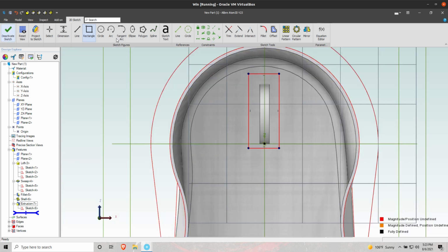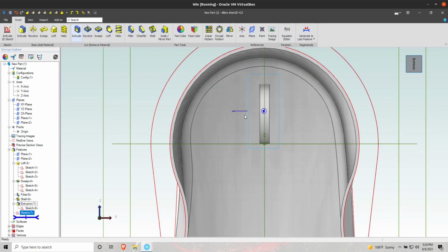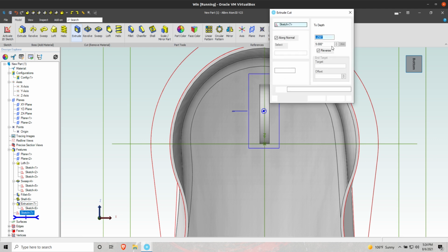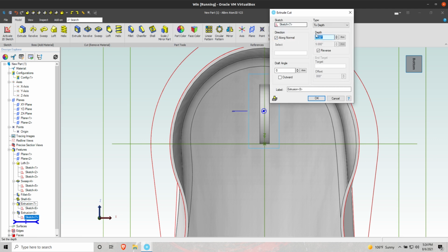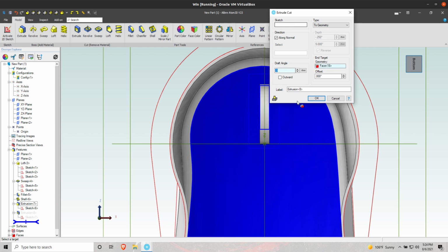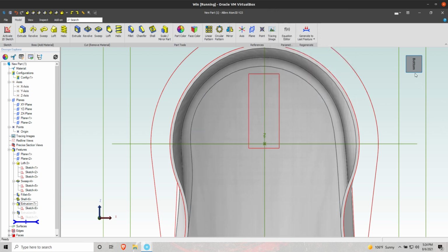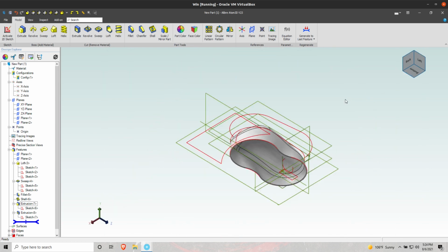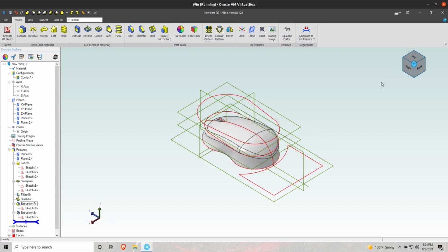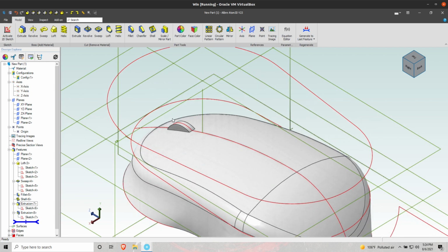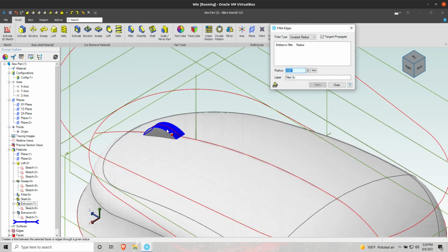We'll deactivate and we'll choose extrude. We're going to say to geometry. And I can choose this face as geometry. And it makes that wheel disappear like a magic trick. So that's a great way to get rid of a feature on a NURB surface if you ever have to do that. Okay. Maybe I'll scroll in and fill up my mouse wheel. And then I think for the purposes of what I'm hoping to accomplish, I think we'll be done. We'll go with a 0.125.